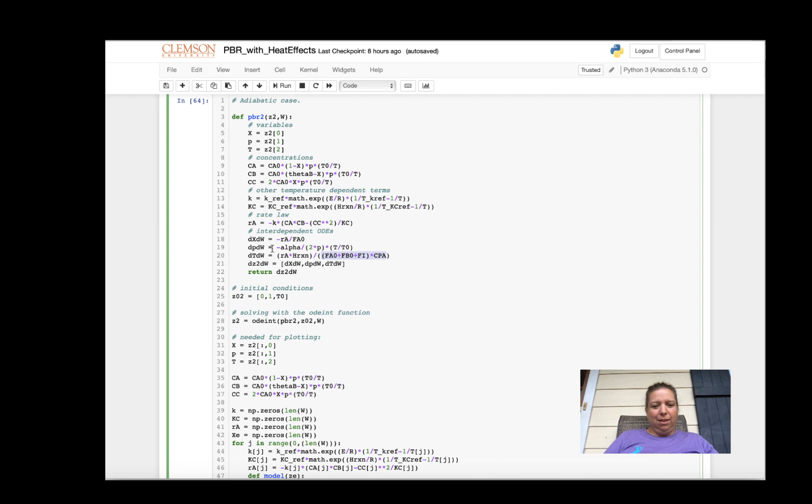So what that tells us is that alternatively, I don't need to write a differential equation here. And in fact, if you look at chapter 11 in the book, you can find a linear expression between x and t for adiabatic reactors. And so that expression doesn't depend on which reactor you're using. You can use it for a PFR, you can use it for a CSTR. That's because energy is a state function, so it doesn't matter how you get from one point to the other, or the path doesn't matter, as long as the point you arrive at is the same for the different reactors.